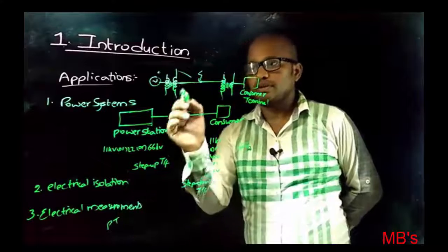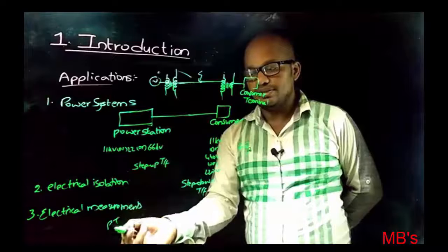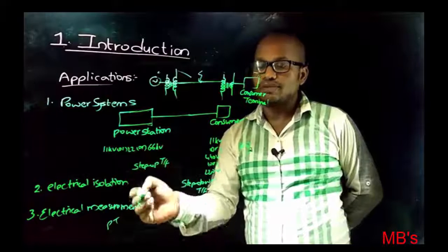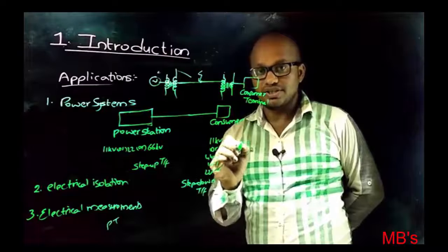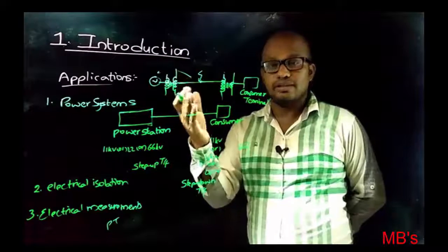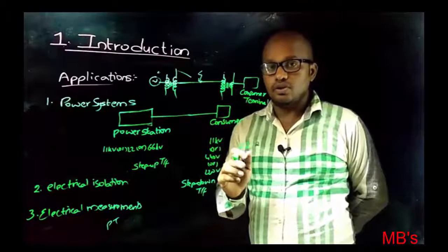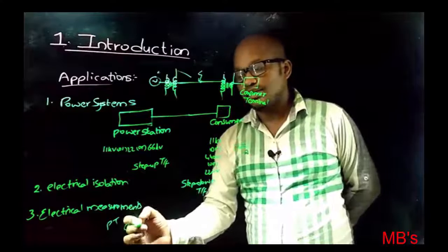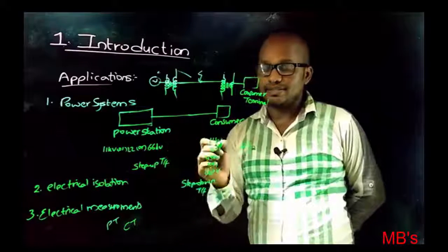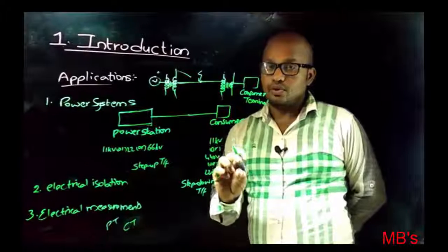This potential transformer is connected to the line which is at higher voltage levels, and this will convert into lower voltage levels which is sufficient for the low voltage range measuring instrument. And similarly for measuring line currents which are at higher current levels with the low range ammeter, CT, that is current transformer, will provide the necessary current which is required for the low range ammeter.